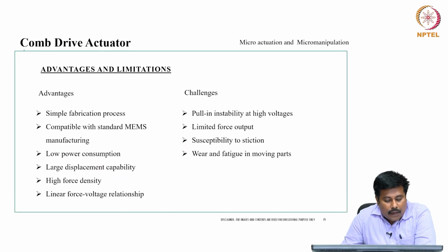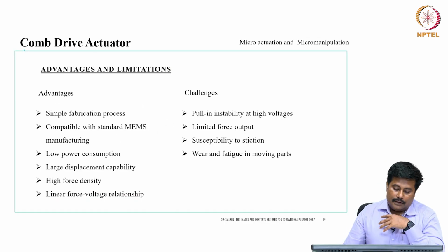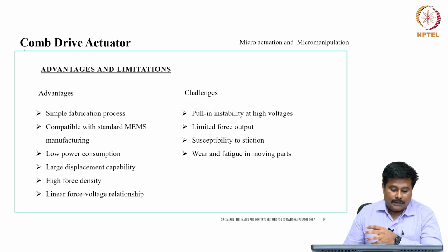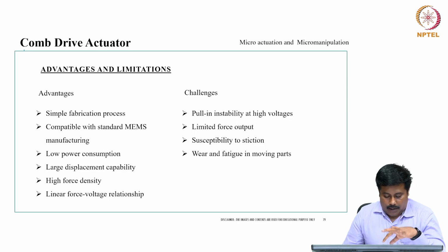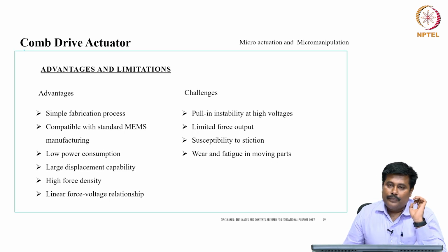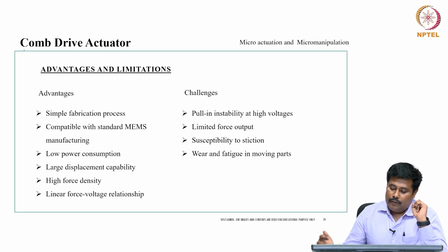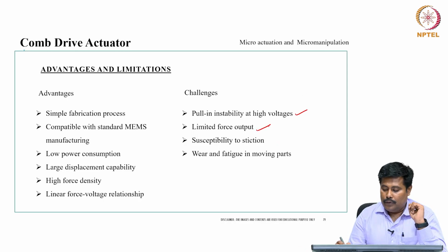With reference to advantages, it has a simple fabrication process. It is compatible with standard MEMS manufacturing. It has low power consumption, large displacement capability, high force density, and a linear force to voltage relationship. From a challenges perspective, it has pull-in at high voltage. It has a limited force output.